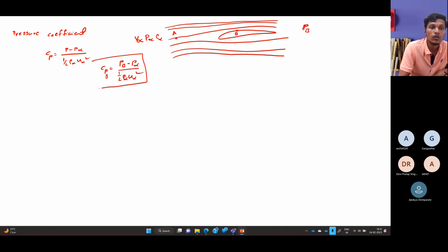Like that I will calculate the non-dimensional pressure coefficient at that point. This is very useful for an aerodynamicist to study airfoils and the pressure distribution over them. Once you understand the pressure distribution and flow physics on it, you can judge many parameters. So this coefficient of pressure is very critical to learn, to dig more into this concept.